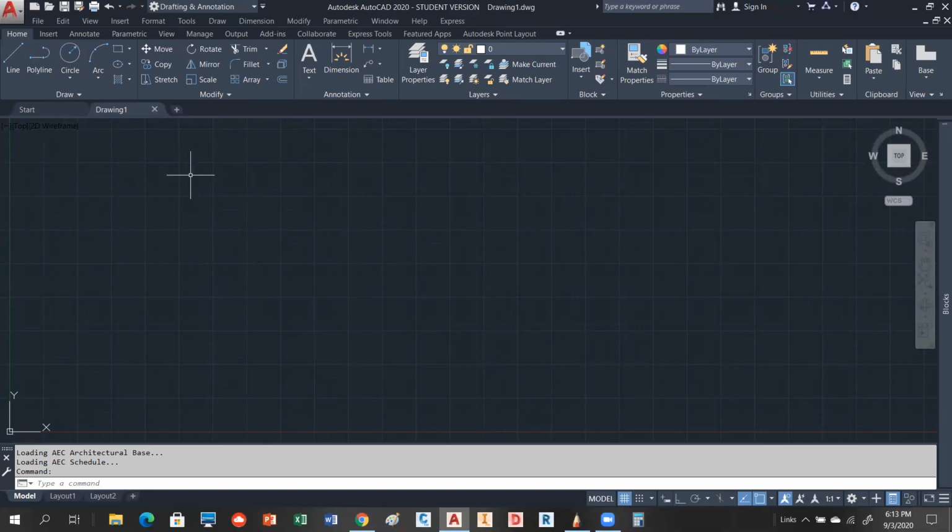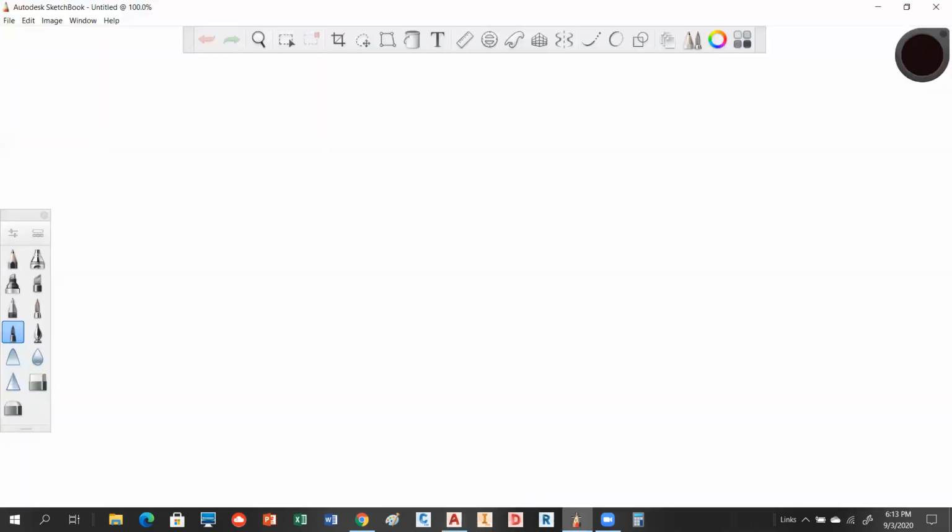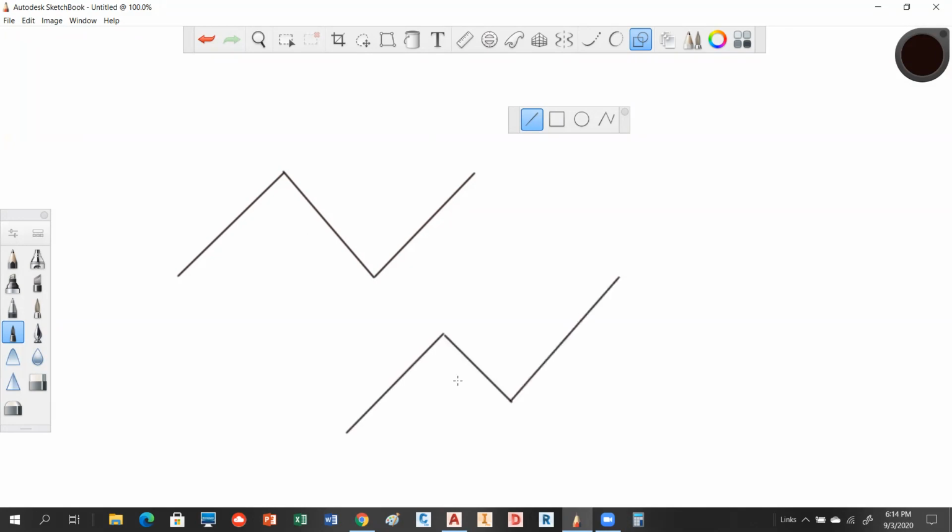So first off, the polyline functions as one object. If you have a line group, so if I draw a line and then another line and another line, if I'm using the line command, these guys are all separate objects. So that's an object, that's an object, that's an object. When you draw a true polyline in AutoCAD, you could draw them right next to each other, as we're going to do tonight. You wouldn't be able to tell the difference between these two guys. They would look identical.